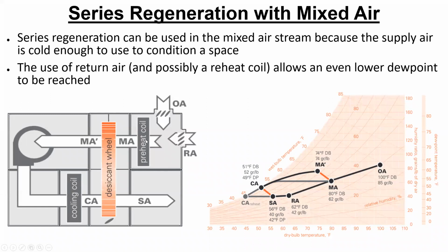Because we did some preheating, or even the desiccant wheel is warmer even without preheating, we kind of provide the heat to a space. In a traditional way, we go from the mixed air, cool it down to the desired moisture content, and then we have to heat it up using a heater to provide the supply air at the right temperature. The gray line shows you the more traditional process, without a desiccant wheel. The red lines are the desiccant process.